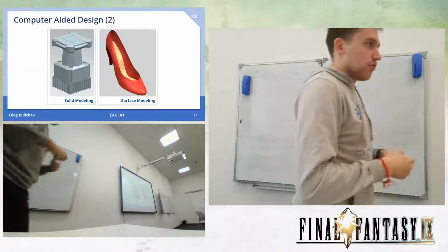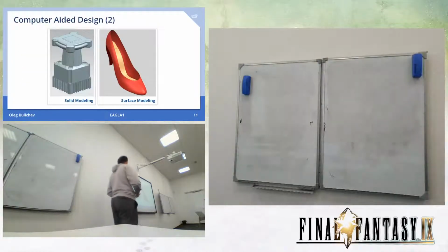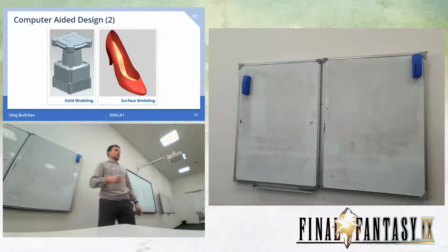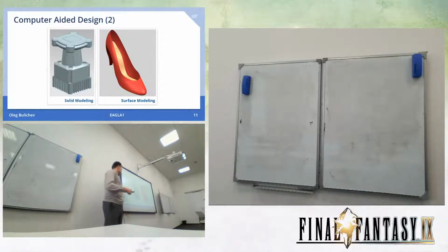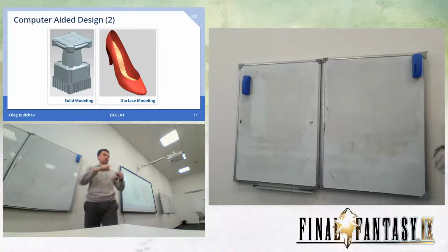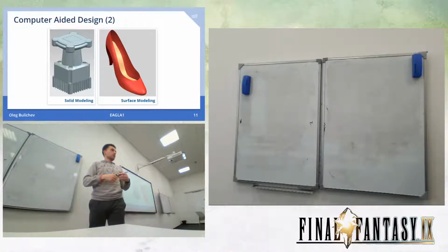Now we are going deeper. Why do we need this parametric form? Actually, we have two possible ways to make the detail: solid modeling and surface modeling. With solid modeling you also can make surface modeling, but it will be a very complicated task. It's not efficient. What is it? We represent our detail as a sketch, so some drawing on a 2D plane.